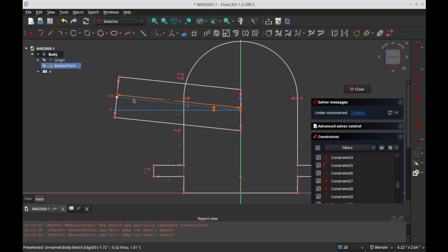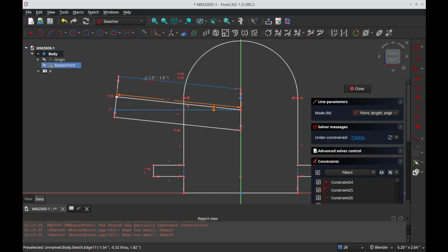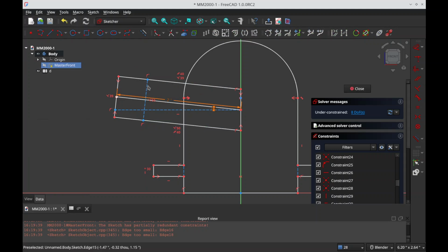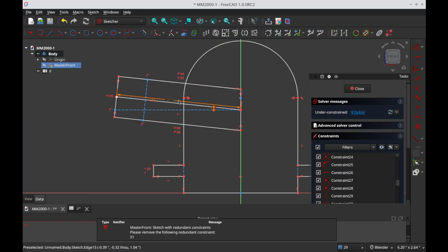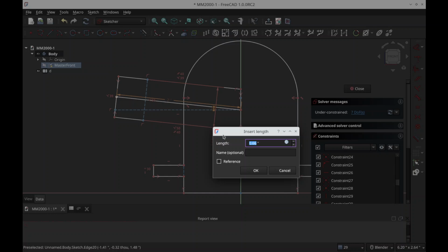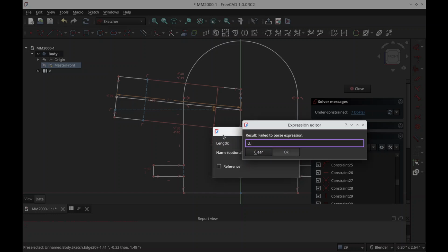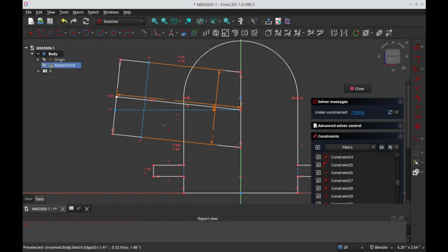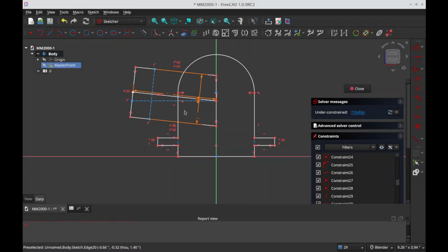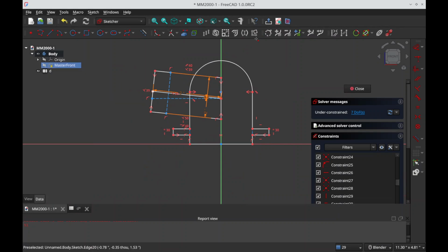Good, right, so if I go to a construction line and bring it down like that, and make it normal here, and make it normal here, remove any redundancies, press D, let's try and get that set, there we go. I don't know exactly why it's failing with the other one, but either way, this is going to be the outer diameter of the pipe. Alright, that should be good.